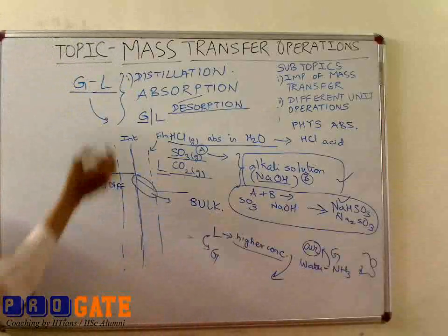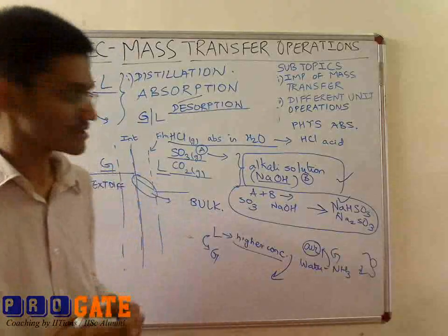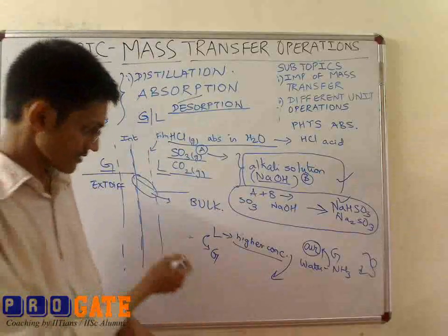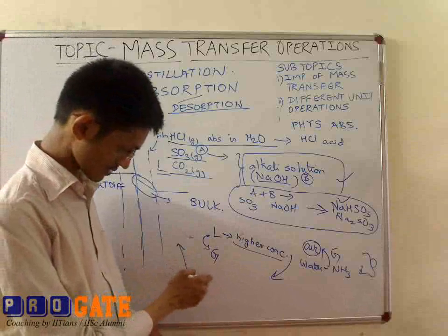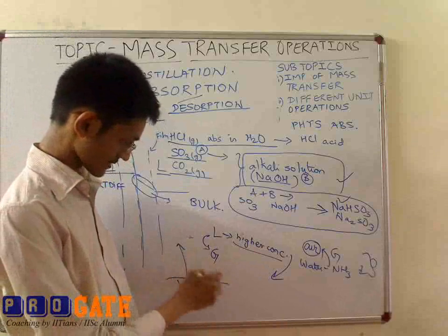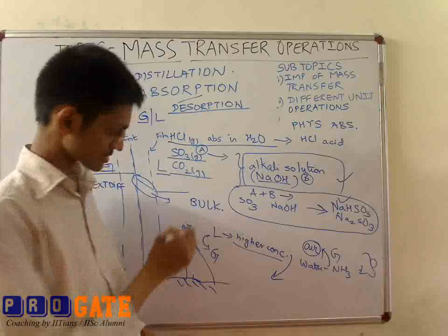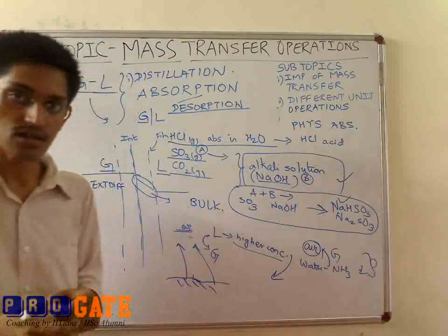Also absorption is characterized when we have humidification and dehumidification of air. Humidification of air, what we mean is water tends to evaporate from the surrounding or the liquid phase, pool or whatever, to the air. So the partial pressure of water vapor in the air tends to increase due to the evaporation of the water.